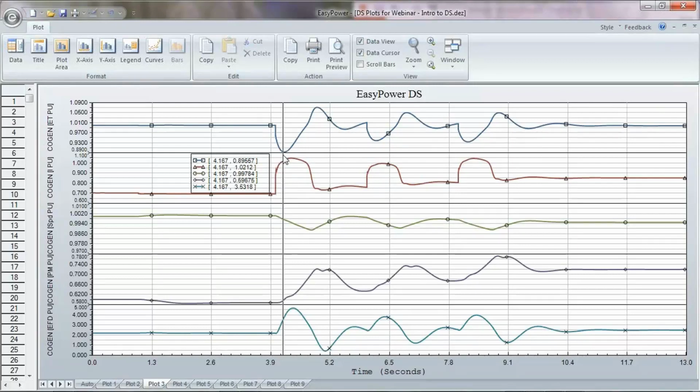For this system, we dip down to just under 90%, at 89 something, and then we overshoot to 107%, so that means we're at 107% voltage for that brief moment in time due to a motor start. And this is a very, very common behavior. I've done measurements on large ships that have isolated power systems.